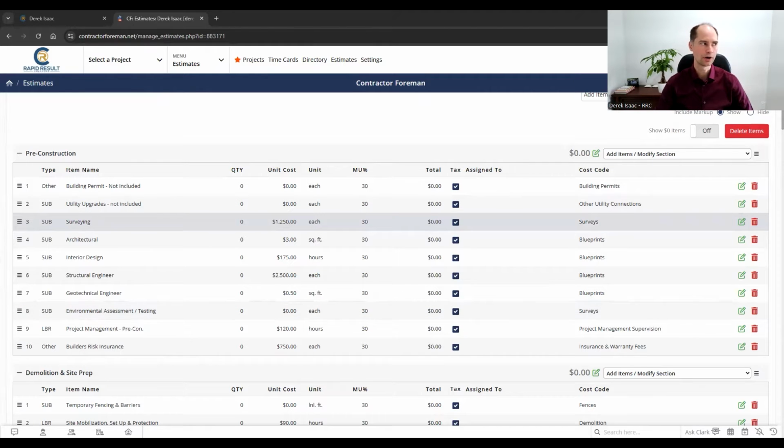Even if you are just bidding on the building part and they're working with a design from somebody else, you still need some pre-construction because you're still going to be spending money on some of this stuff. Even if the architect or whoever is taking care of some of it, you still want it as a line item with a zero cost, saying not included, not applicable, or to be supplied by others, so that it's very clear and there's no later, I thought you were doing this. No, we didn't have this in our quote. Well, why not? So stuff like that is outlined specifically.